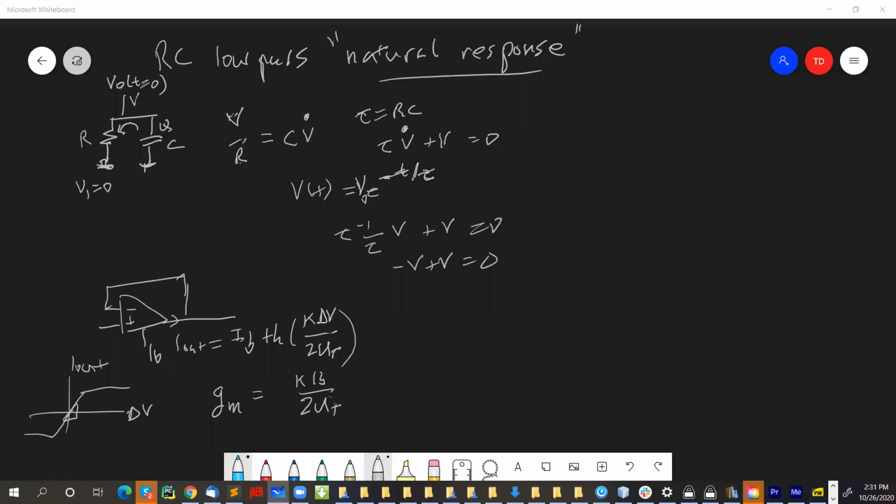There's a question from Keatsy. Why is the output conductance of the wide range transamp lower than the transamp? What do you mean lower? Oh, yeah, that's related to last week's circuit. I'll answer that later if you don't mind. But basically, the short answer is the output conductance is lower because the output transistors are longer, and so they have a higher Early voltage. Otherwise, there's no reason that the output conductance should be lower. It's because the amplifier is designed to have long output transistors to make higher voltage gain.